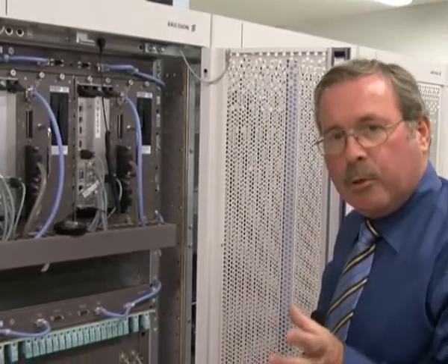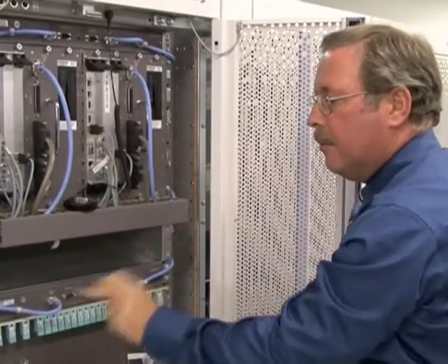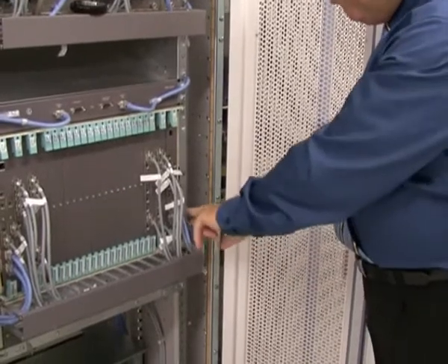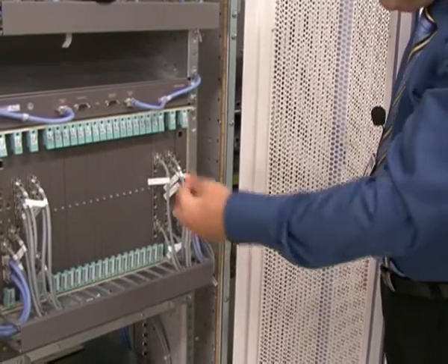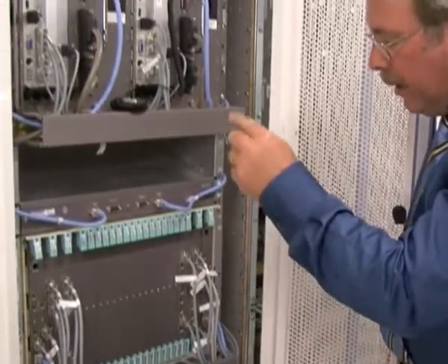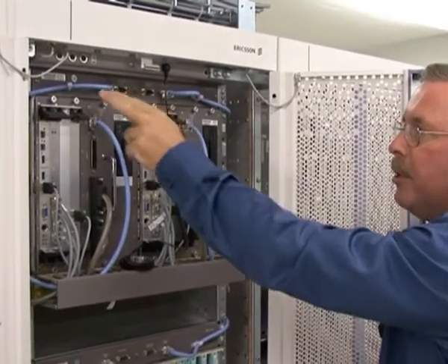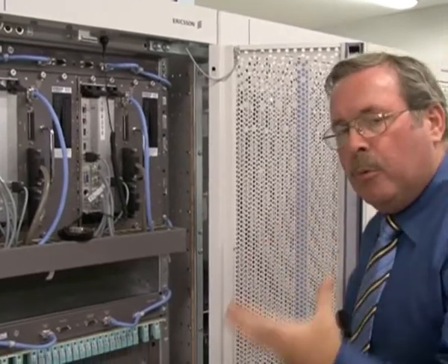In this particular switch or exchange, we see that we've got many low current DC feeds to the various units. But if one unit were to generate transients, switching transients, sending them back down the power supply, then these would not, for example, come back up here and disturb this unit. So the high ohmic distribution would remove these switching transients, and this is the basis of the core power solution.